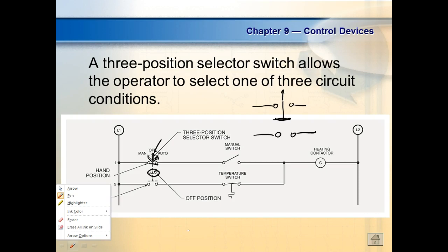Now, the big difference between a solid dot and an open dot, what's the difference between this guy and that guy? It's a terminal. It's what we connect to, right? So on your input devices, these right here are going to have the open dots, not the solid dots. So in this class, all your labs are drawn. So if you use the selector switch, it's going to be drawn, right?